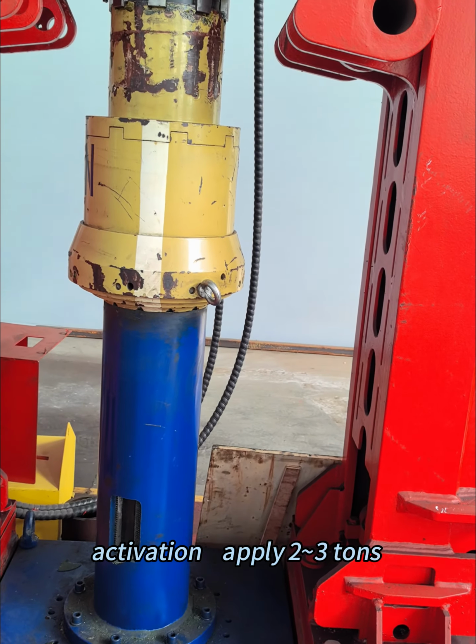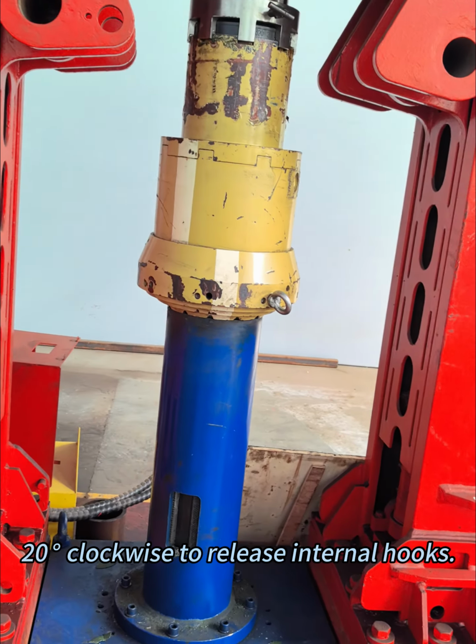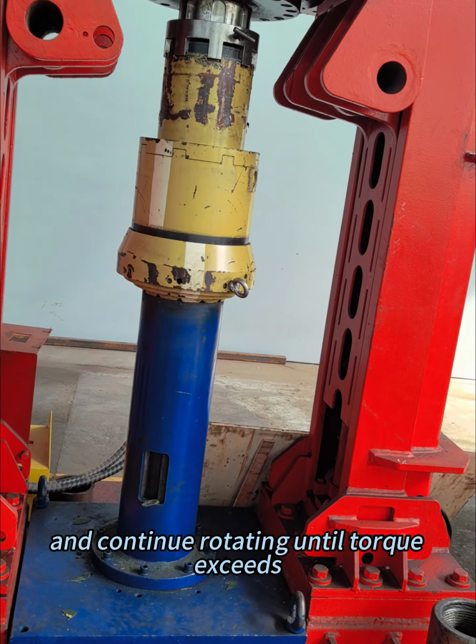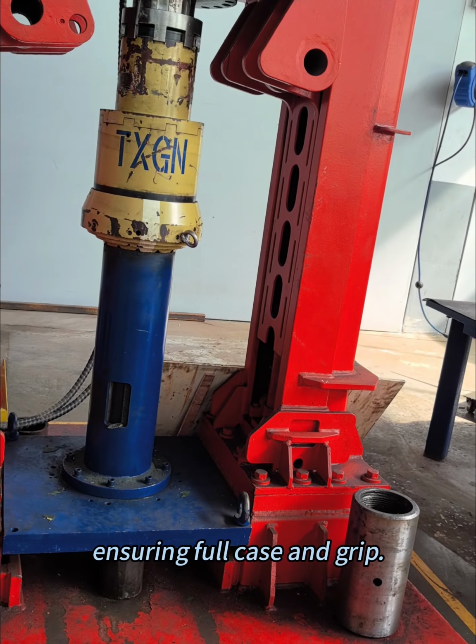Activation. Apply 2 to 3 tons of downward force and rotate approximately 20 turns clockwise to release internal hooks. Restore natural suspended weight and continue rotating until torque exceeds 4 kN, ensuring full casing grip.